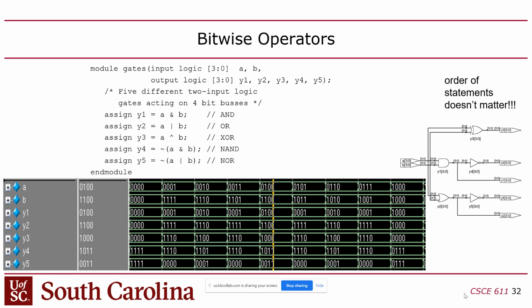Okay, so now let's talk about some multi-bit signals. Obviously, your designs will not all be single bits. The program counter is going to be 10 bits, your instructions are going to be 32 bits, your registers are 32 bits, and your control values will be different widths, right? So can you have multi-bit signals? Yes, but this is a strange syntax, the way they declare these.